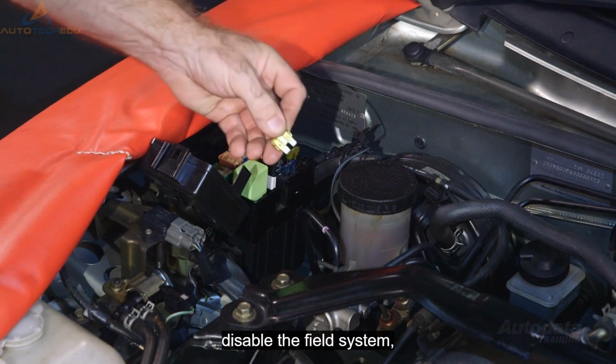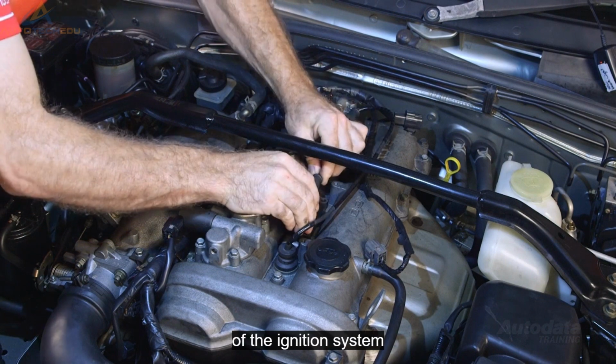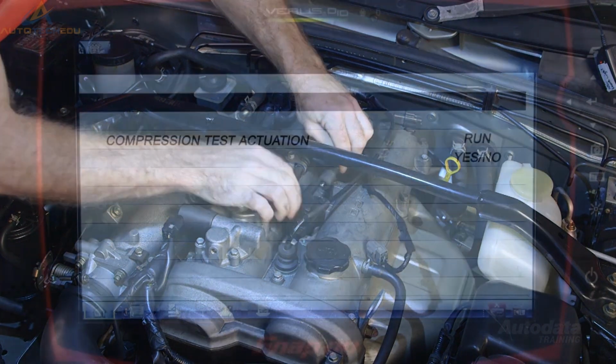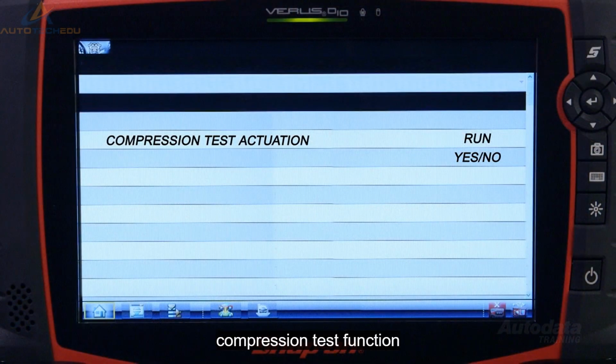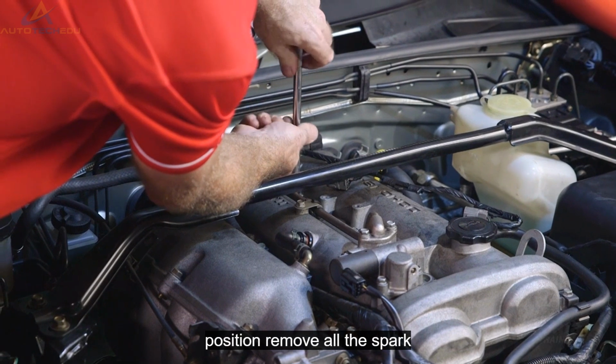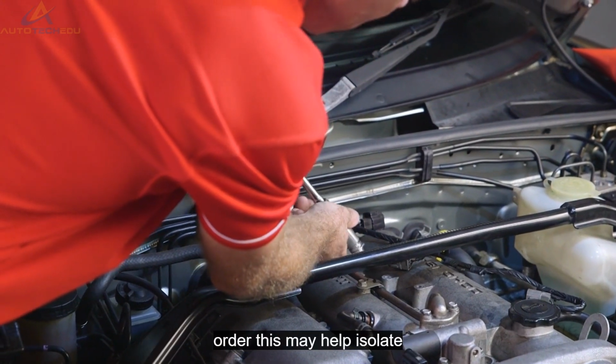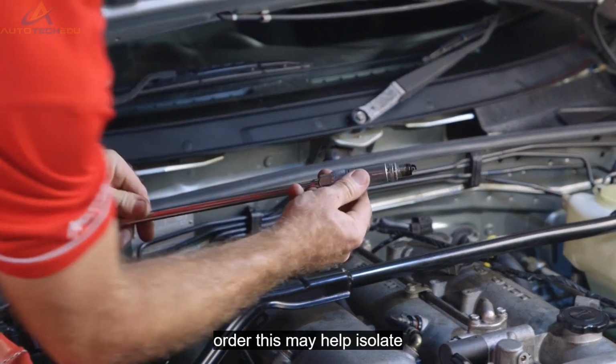Disable the fuel system. Disable the spark by disconnecting the primary side of the ignition system. Some scan tools have a compression test function. When selected, it will disable the injection, spark, and hold the butterfly in the open position. Remove all the spark plugs and inspect. Always keep them in cylinder order. This may help isolate a cylinder fault.